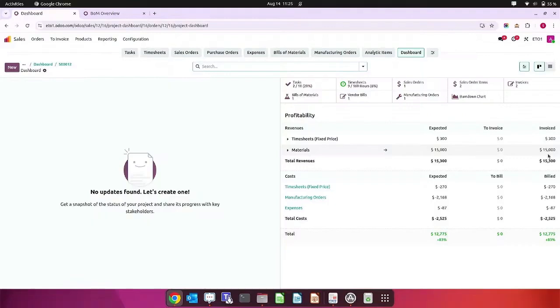Second thing, here we can use the concept of PLM also. If 5 to 6 of your products are similar, and in some of them some modification is required in terms of quantity, then we can use the concept of PLM with those ECOs. So there is no need to create a bill of material from scratch. You can add, you can remove, and your bill of material will be on hand.